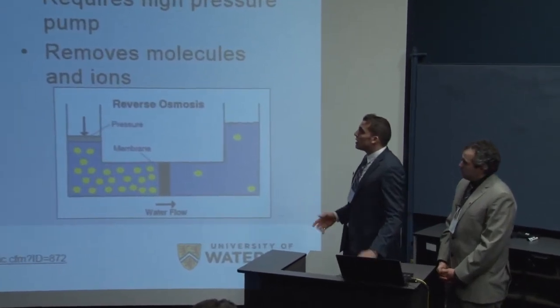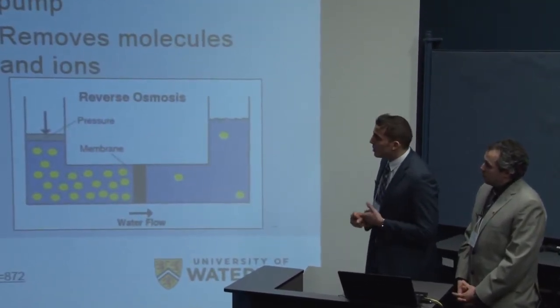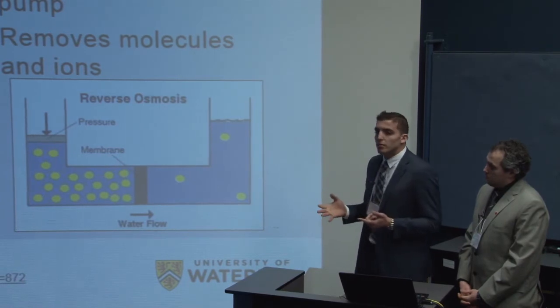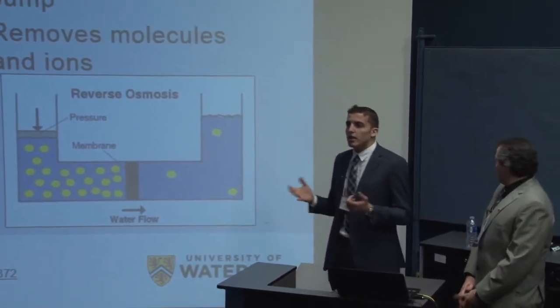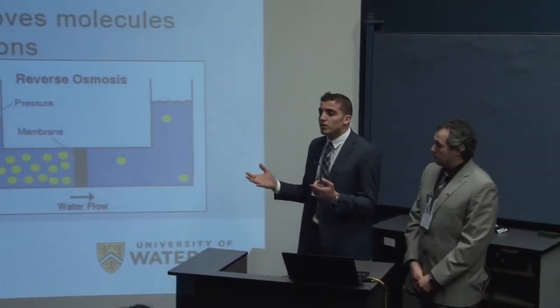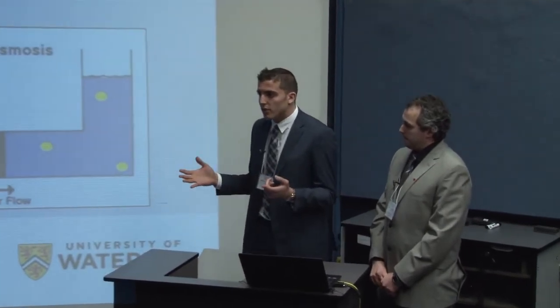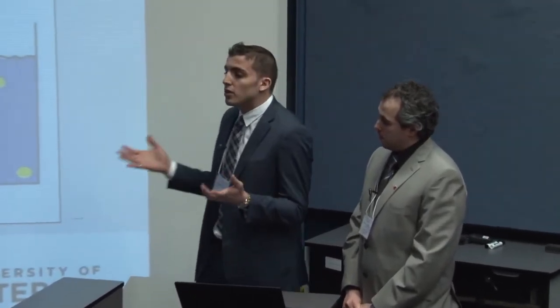CDI extracts ions. It's energy efficient below 10 grams per liter, and it's a pure physical process, which is really important for the lifetime of your material. There's no chemical reactions occurring. It's just based on electrostatic forces, which is a physical process, usually means a longer lifetime.